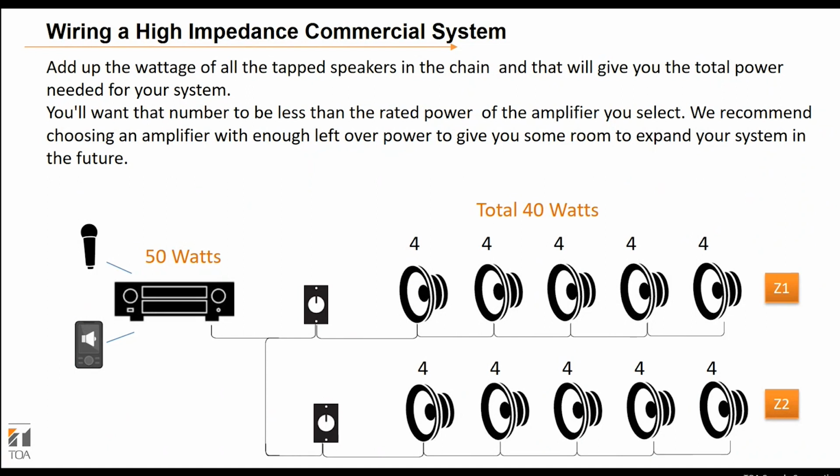We always recommend also to choose an amplifier that has plenty of power left over to give you what we call headroom. Not necessarily to expand the system, but more to protect the system in case of peaks and valleys. So audio has a tendency to peak every once in a while, and what that means is that it's going to drive a little bit of extra power into the system, and that headroom is going to allow the system to absorb those peaks without having any excess pressure on either the speakers or more particularly on the amplifier. If you're running things at max on the amplifier, if your system peaks, then you're actually overdriving the amplifier. You're potentially damaging the amplifier.